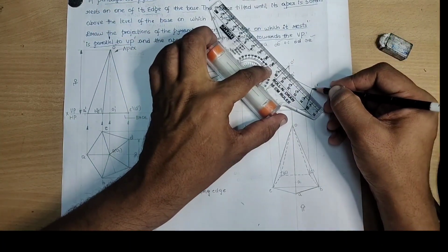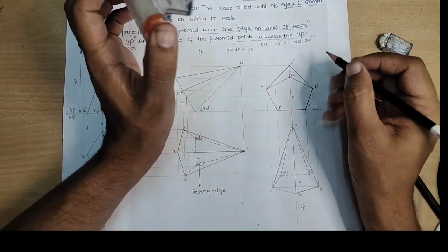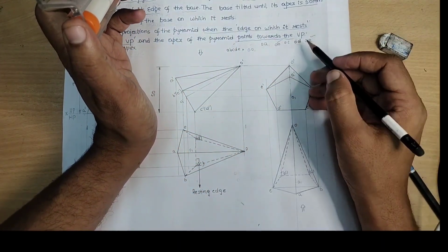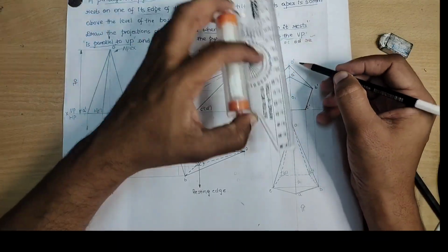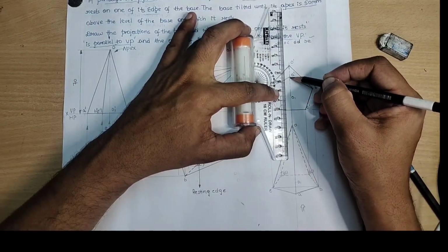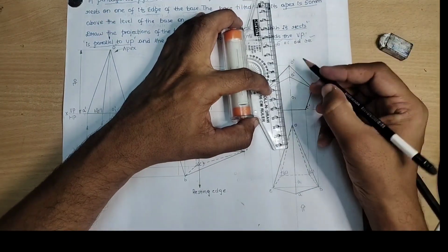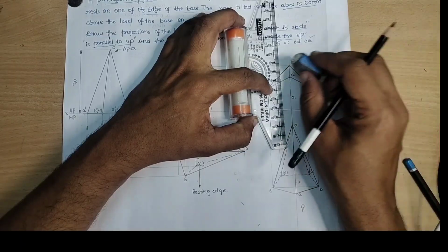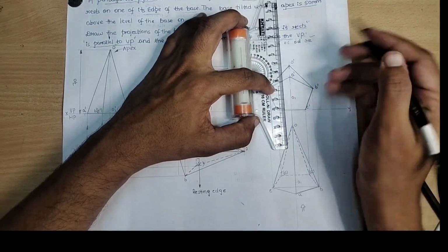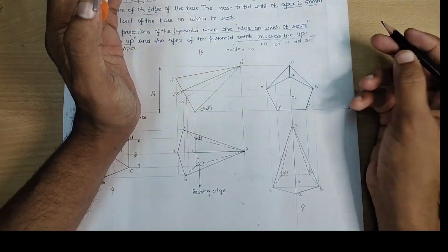By the same explanation, O to B also forms the outermost boundary. It's visible. Next, what is the condition of O to A? O point is here, A point is here. A point is extremely close to the observer. Hence, O to A is visible. But O to A is already shown as a part of the axis line. Erase the axis line and show it as a continuous, visible line.